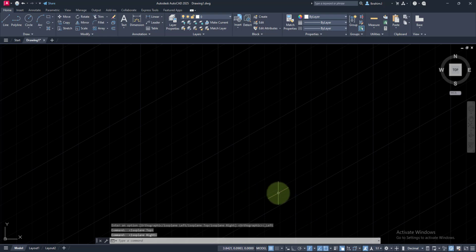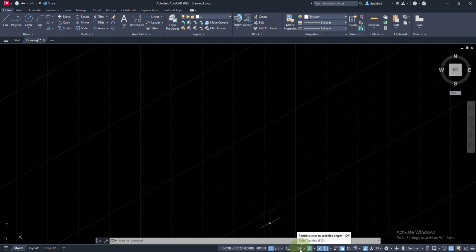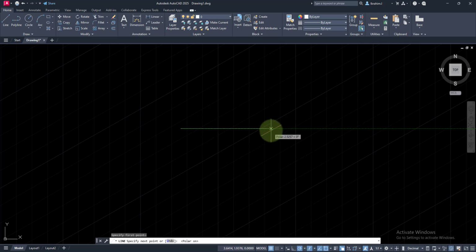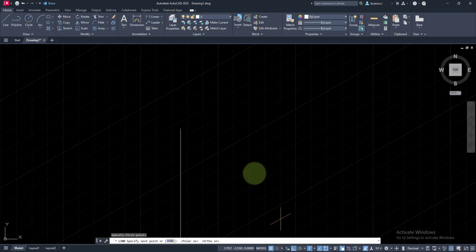All these views are the views required for you to create an isometric drawing, right? Also, one thing we try to have checked is on our line. For example, I'll start a line command. While I have the command on, notice something. My line is just creating like a normal polar object, right? There's nothing really snapping. Most of the time, whenever we are creating an isometric drawing, we try to be on Auto mode.